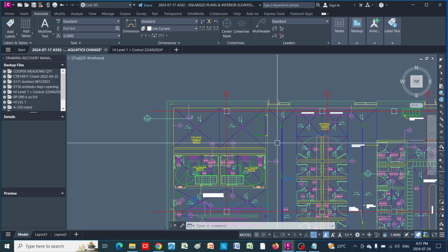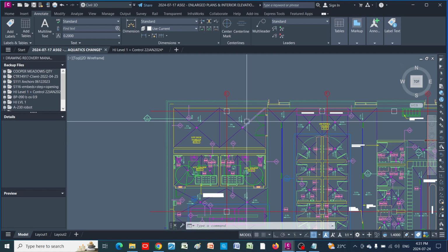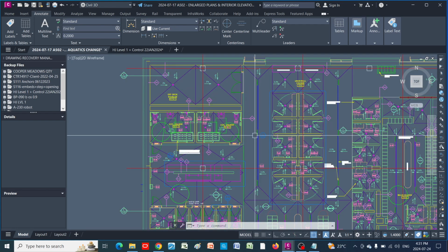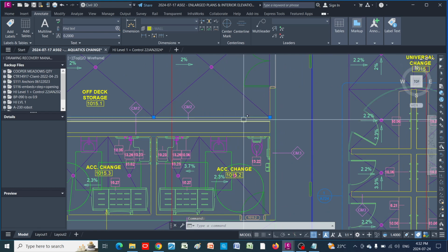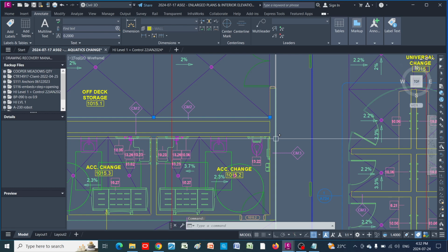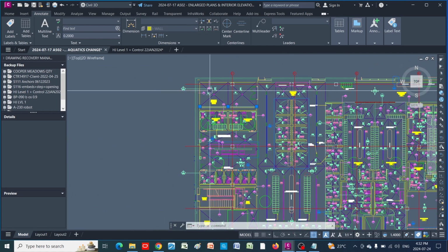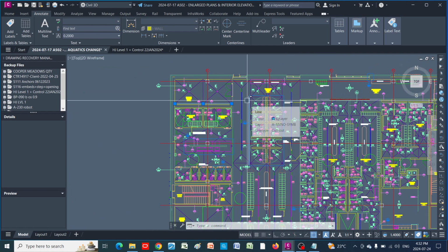Nowadays, thanks to the digitalization of layout, all you need to do is get the CAD file, put it in your robotic total station, and go to the job site. Just pick which line you want to lay out, and it's gonna lead you to that layout element that you want to mark.